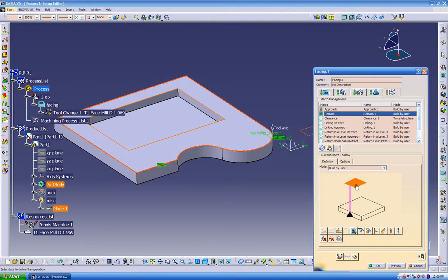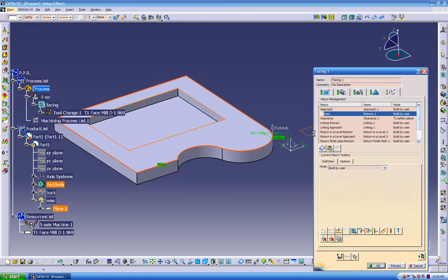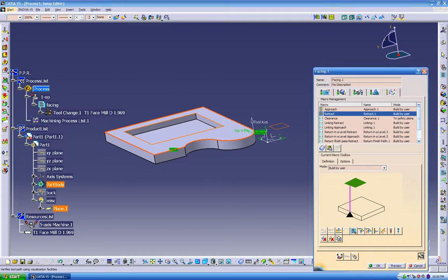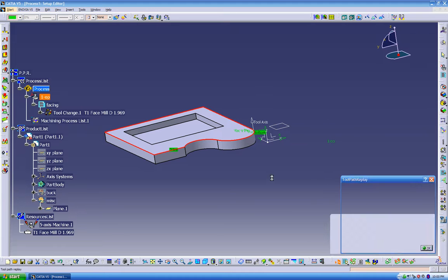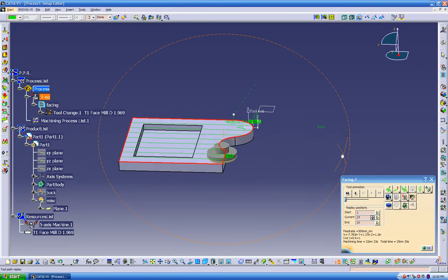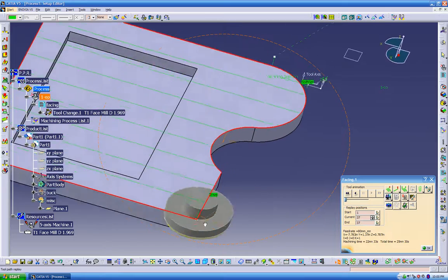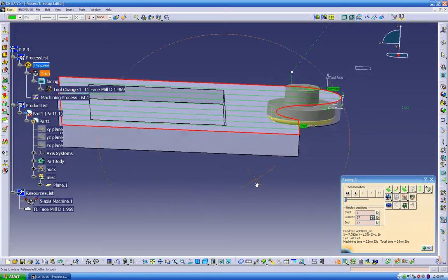And then retract, I'm going to do the same thing. Once the tool goes around, it's going to retract from here and go up to the clearance plane. So I click on the plane, then click on the clearance plane, then you come down here and we do toolpath replay. So this is our tool. But see right now the tool is right on top of the part, and I don't want to plunge right on top of the part, I want to plunge outside.